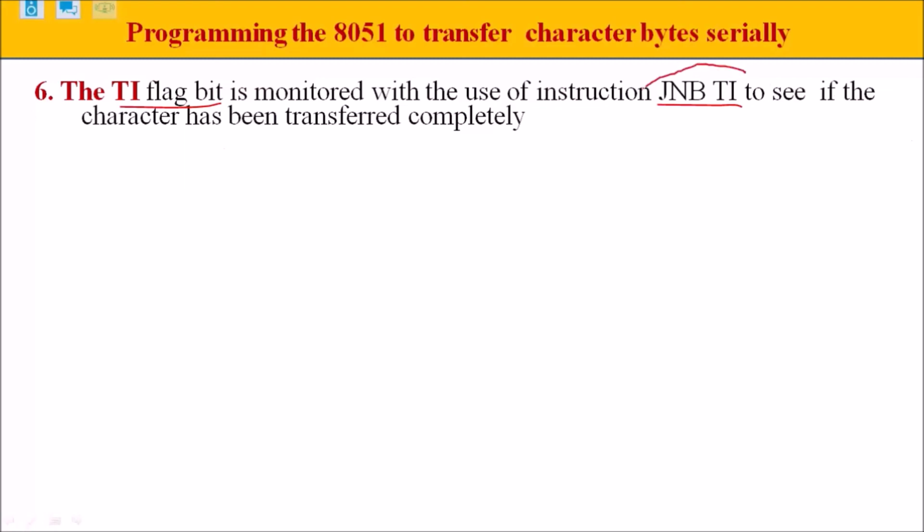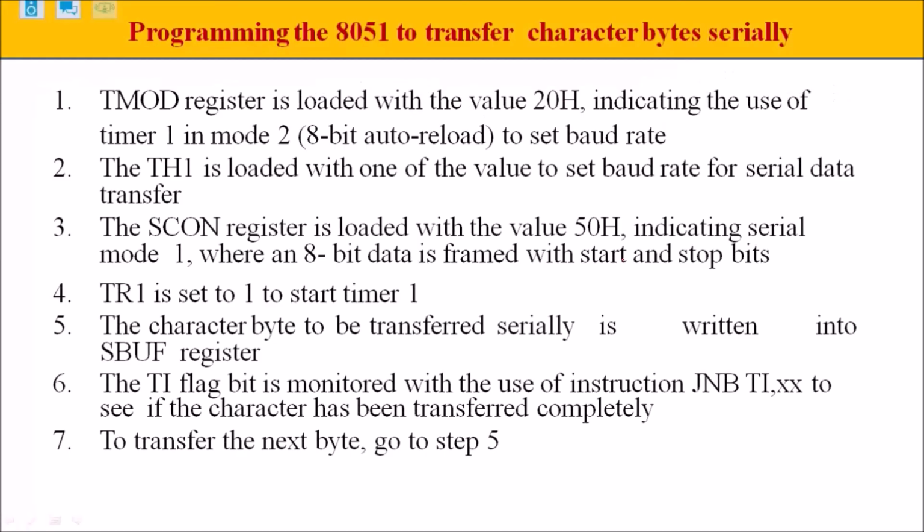So check this TI bit. If it is 1, go to the next instruction, clear the TI flag. If you want, transmit another character. So just go through this. All these steps are written here.